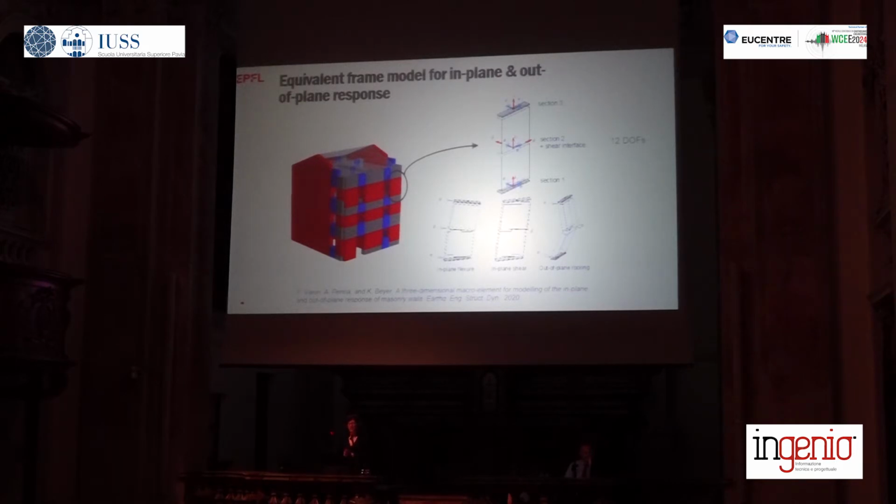and then adding also some flexural degrees of freedom for the out-of-plane response, so that at least we can capture the simple out-of-plane bending moment where we have a hinge at the mid-height, or of course then really the whole overturning of the walls. And that is really the work by Francesco Banin in his PhD thesis.